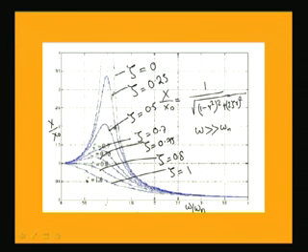For an undamped system, you are observing that the maximum amplitude occurs at a frequency omega equal to omega n, and for the system with damping, it occurs at a value slightly to the left of omega n, that is, omega slightly less than omega n, you are getting this maximum amplitude. And when omega by omega n is very large, then the response amplitude is very small.